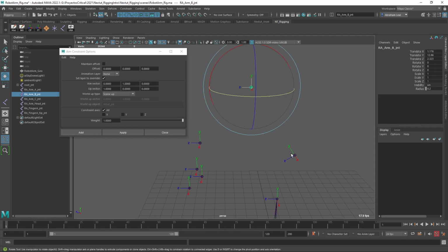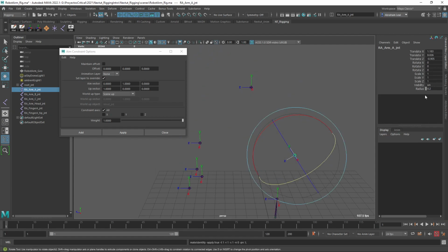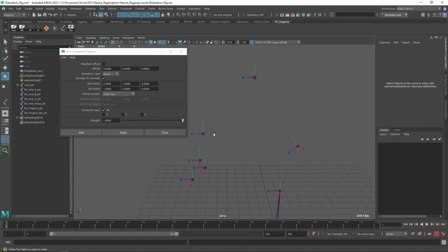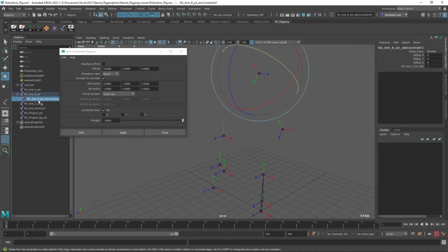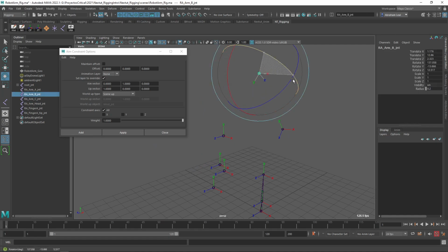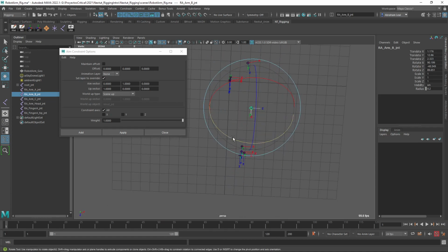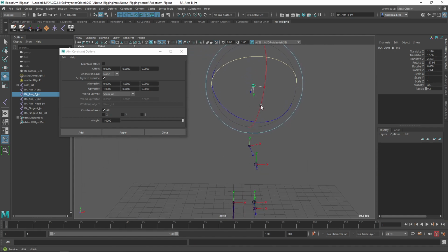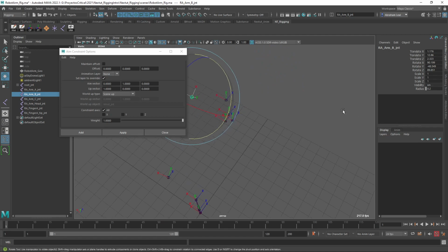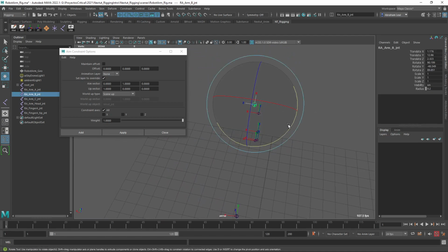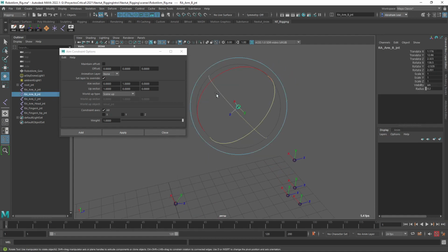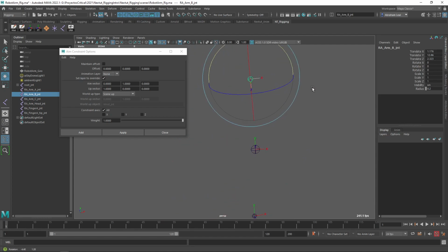Now this one, I'm going to do the same thing. Of course, we're going to do a freeze transformation to clean everything. We're going to do the same for all of them, actually. And then we're going to say driven, and apply. So now it's pointing with the y-axis. We don't need the aim constraint anymore. And we're just going to rotate this thing so that the x-axis is pointing to the side. It should be... Let me properly align this. There we go. And we're, of course, going to delete our freeze transformation. So now you can see that the y-axis is nicely pointing to the next section.